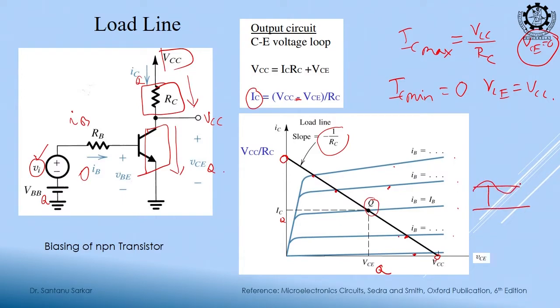Now, you will add a small voltage, so that you get amplification, right. So, if you see, say this is my VB and this is a small voltage source. Due to this small voltage source, what will happen? You will have a small input current IB.